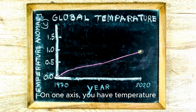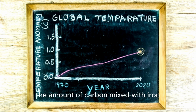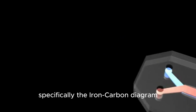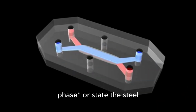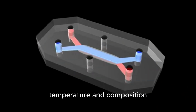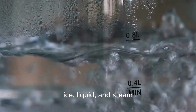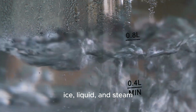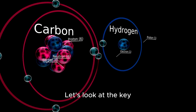So what's a phase diagram? Imagine it's a recipe book for steel. On one axis, you have temperature, and on the other, the amount of carbon mixed with iron. This chart, specifically the iron-carbon diagram, tells us exactly what phase or state the steel is in at any given temperature and composition. Think of these phases like states of water, ice, liquid, and steam. For steel, we have different solid forms with unique properties.